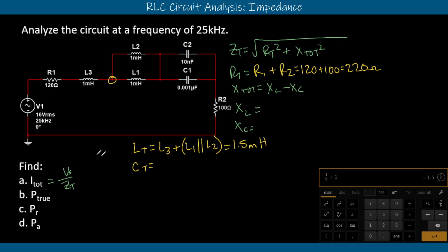Right? So let's do the same thing for our CT here. We can solve for that and say that our CT does something similar, but it skips through the inductors. We go through the inductors and end up at this node branch here. This node branch is like the plus thing in the middle, right? So we know that whatever's before that node, because they're shared right there, it's going to be in series.